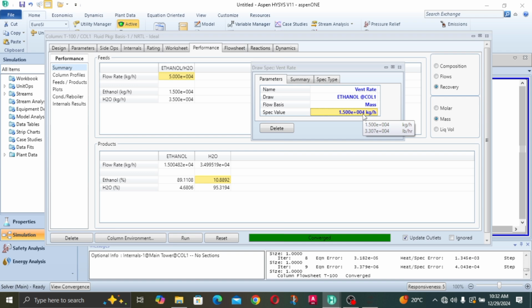With this, you could say we have a good amount of water. We have extracted a good amount of water. Let's go 17,000. 94%. It's dropping. So if you're trying to find a balance, I think this would be a good point to find a balance. 17,000, where we have 99.9% ethanol and 0 predominantly water inside the ethanol stream, which is desired, and then we